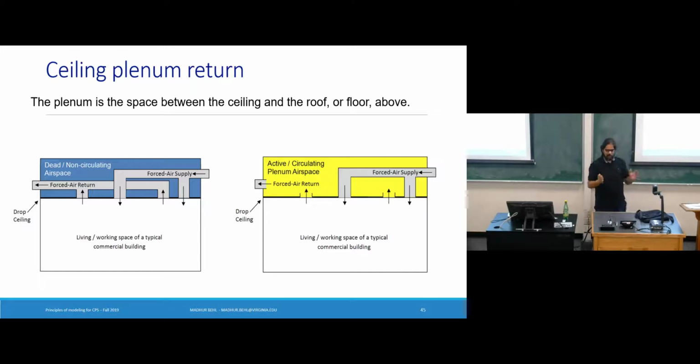Sometimes, especially in older buildings or in very simple home constructions, what you will find is, rather than having a dedicated network of return air ducts, as is shown on the left-hand side, there's no dedicated network, but instead there's an entire space itself from which this air can be returned. Right? So we are just sort of taking the air back into this yellow zone, and this entire zone behaves like the return air system in this case.